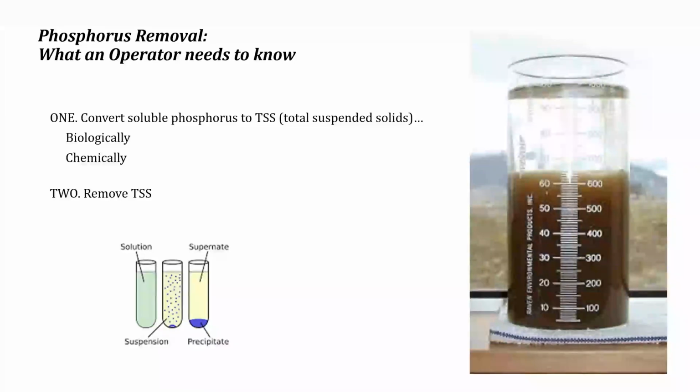So our concern, our process control, and what you'll hear me talking about, is monitoring that soluble fraction. We're permitted on the total, but our process control is all about understanding how much of it is soluble, and then whatever's in and with the TSS and whatever portion of the TSS goes out as effluent TSS is going to contain some fraction of phosphorus.